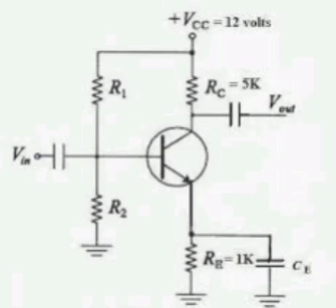The question is, find the voltage V0 in the circuit shown in the figure using source transformation. Also find the power developed by the 250 volt voltage source. An element in parallel with an ideal voltage source is redundant. An element in series with an ideal current source is redundant.